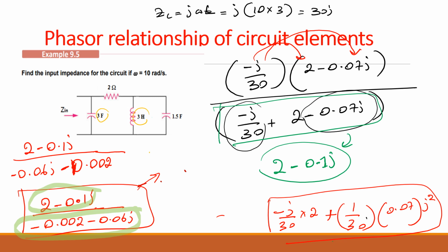Do you understand everything that we have done so far? We just converted the resistors, inductance and the capacitance to impedance. So when we have everything in impedances, we can add them considering parallel and series connection. We haven't finished that part yet.